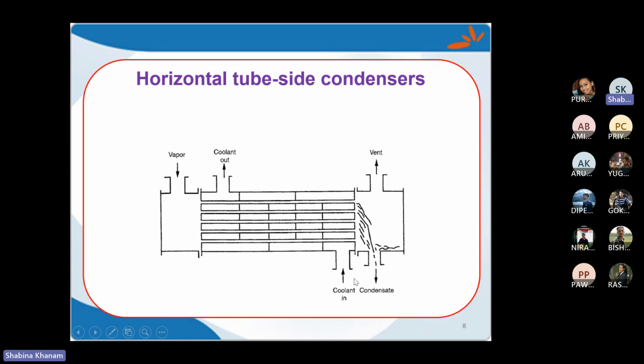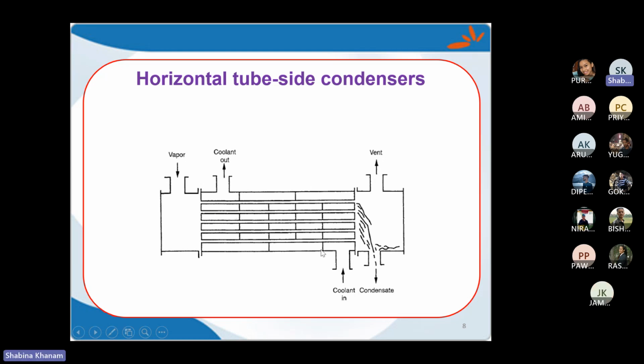And obviously shell side I am having the coolant, so that is inlet and outlet, and then in that case baffle will be normal. Okay, because movement of coolant will be like this. Okay, not side to side. Okay, in that case from side you will see these line to be covered till here.